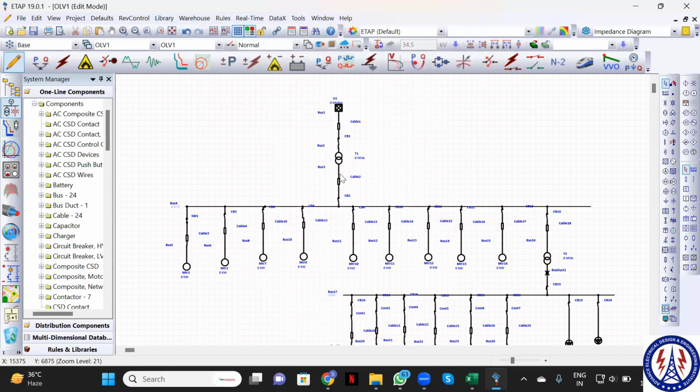Now we will provide the rating to the motor. See, the standard for the motor is up to 160 kilowatt. We are taking it as an LV. If our motor is VFD control, we can go up to 315 kilowatt and also model it as an LV. What is the reason? Because in case of VFD, the starting current will not be there, so basically there will not be a drop. So that's why we are using that. More than 160 kilowatt, we will provide it in the HV.